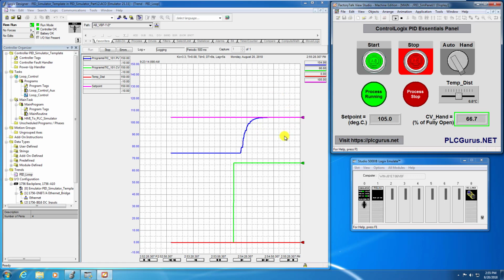So I think this time, in order to get us into instability, we're going to actually have to hit it with a disturbance. So let's hit it with that step input of 10 degrees C. So we're adding heat energy into our process from an external source, and it should follow now that our output actually starts closing off our valve, right?